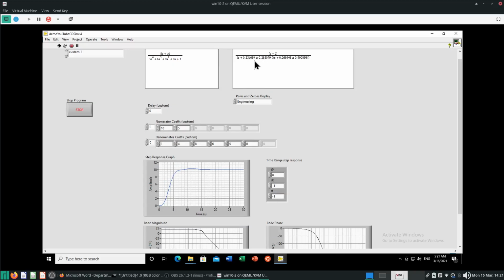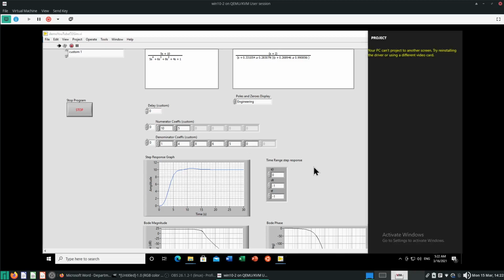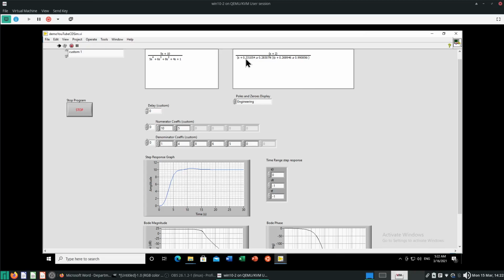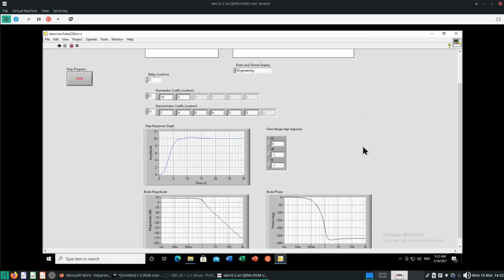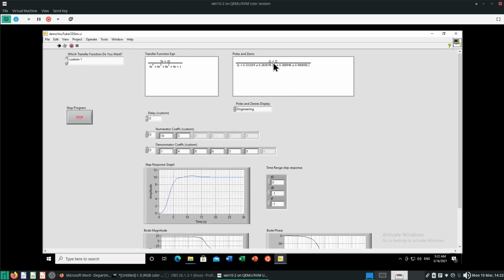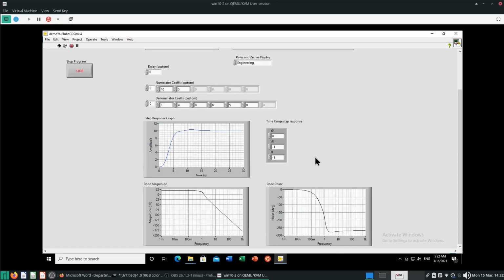And if you look at the poles, there are actually 2 places where... okay, let's put some context first. If you have a pole at a certain frequency, the tendency is for the Bode plot to start sloping downwards at 20 dB per decade. That I assume you should know. If you have a pole at a real part, it should slope downwards at 20 decibels per decade. If you have a zero, it should slope upwards at 20 decibels per decade.